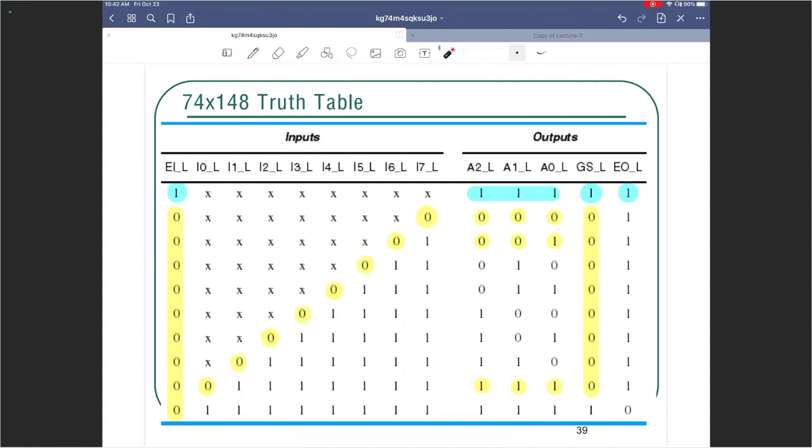Well, it turns out got something underscore L is active when one input is active, or some other inputs could also be active, right? Because I6 could also be active at this point, but it will give priority to I7. So got something is simply, did you get at least one input active or not? But for the last case, when no input is active, our got something underscore L output is inactive. Note over here, the enable is active as well for the last case.